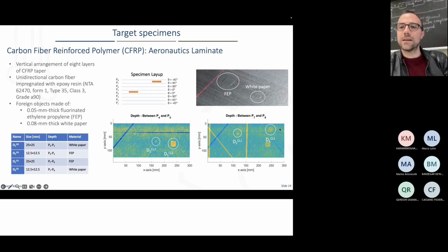And we made a scan with a profilometer to get the perfect characterization of the size of the material before finishing the processing of the material itself. So before the polymerization, when you make an inclusion of some material, for example here, you are still able to detect it visually, as you can see. But then at the end of the polymerization process that is made with an autoclave at specific pressure and temperature parameters, everything is completely flat. You are not able to detect any inclusion of materials. Okay, so before making a polymerization, we scan it with a profilometer.